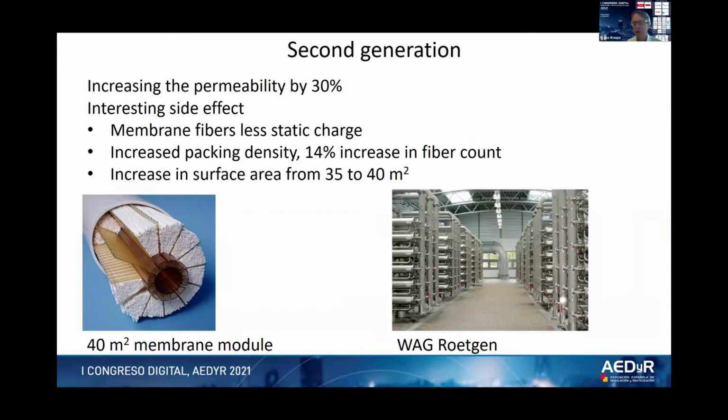Within EXLO, we have an R&D department. The R&D department not only improves the membrane modules, but we also look at improving performance of the system, the operating conditions of the system, modifying those to lower energy consumption or to lower chemical consumption, but also different ways of installing the membranes. So one of the first major improvements was that we increased the membrane chemistry to improve the permeability by 30%. So exactly the same physical shape of the membrane in one step could produce 30% more product flow.